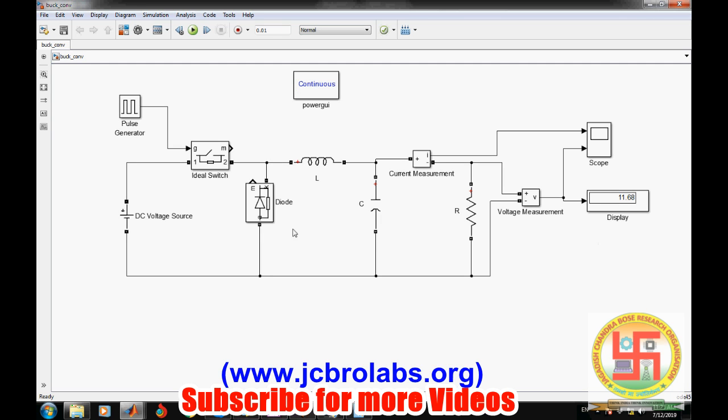Yes, it is again giving the same required voltage at a different value of R. So from here it is evident that if we want to increase the value of resistance, we have to decrease the duty cycle. That means from this duty cycle we are changing the equivalent circuit of this buck converter. The internal impedance of this buck converter is dependent on the duty cycle, and by changing this duty cycle we can change the impedance offered by this buck converter to the source.